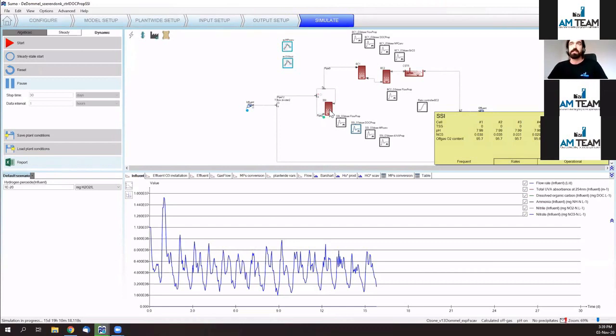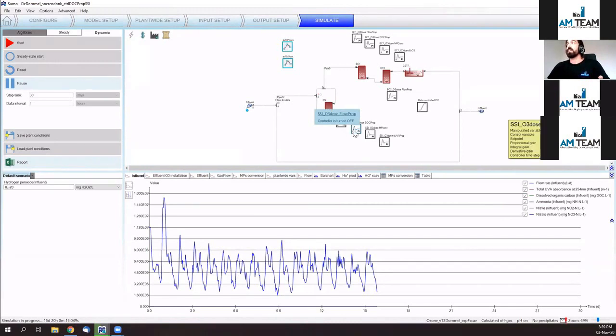So in here, you have the gas transfer of the side stream injection, which very efficiently injects ozonated gas at a certain concentration, depending on the generator in use, and can be controlled with different control strategies. Here you see different examples of controllers, like a flow proportional controller, DOC proportional control, even micropollutant-based controller,